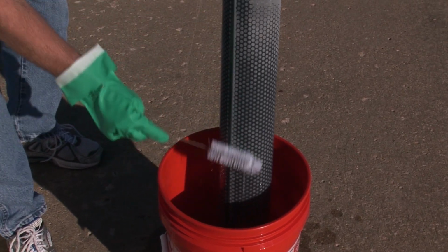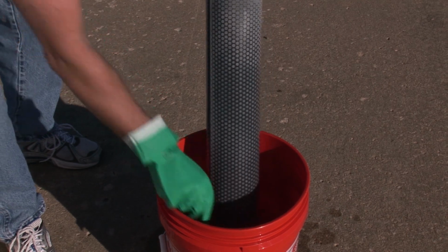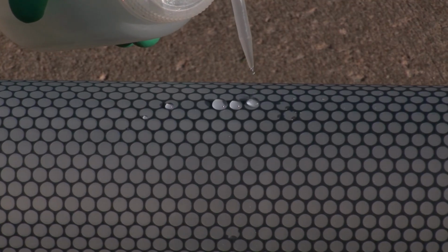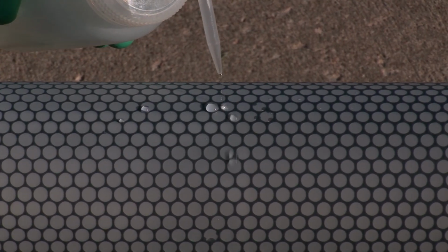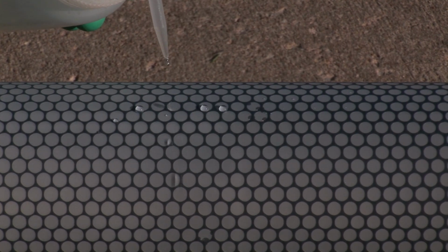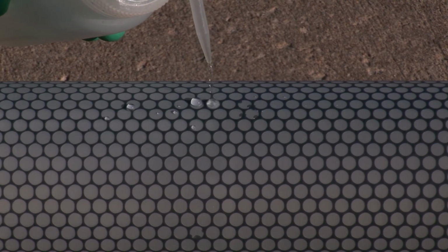While the element is still fuel wet, each used cartridge must be tested for its ability to repel water. Hold the cartridge horizontally. Drip clean water on it from a height of no more than 3 inches. As you rotate the cartridge, water should bead and roll off the properly cleaned element.